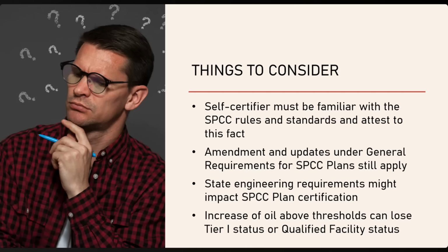In summary, some things to consider when considering the use of a Tier 1 or Tier 2 option for compliance. The self-certifier must be familiar with the SPCC rules and standards and attest to this fact. There's also the issue of whether there are state regulations that need to be integrated into the SPCC plan. This might present an additional challenge to a non-professional. Amendment of the plan and updates under the general requirements for SPCC plans, that is in 40 CFR 112.7, still apply to the Tier 1 and Tier 2 plans.